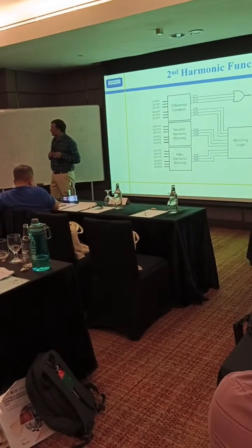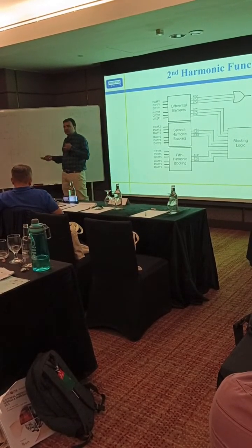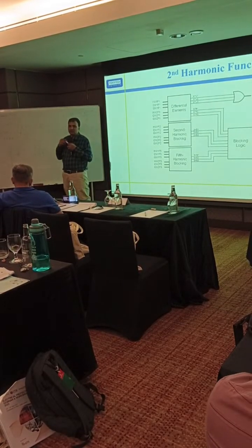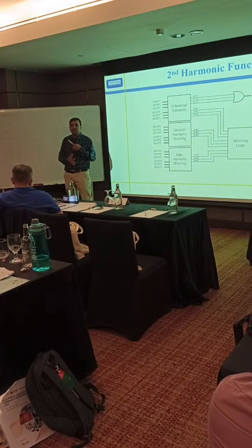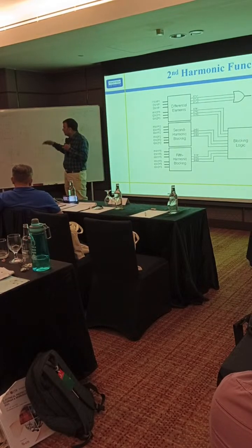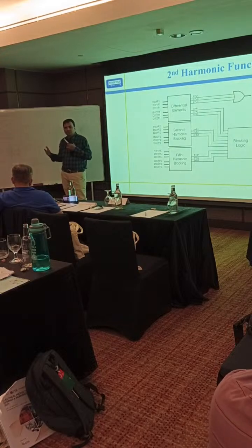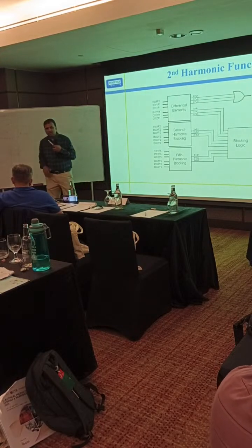So this way, the reason why we have unrestrained differential is because if differential current is much higher, then we should protect our transformer first. That is why at a certain limit, the value is generally 8 times to 10 times. That is why it is kept at a higher place.